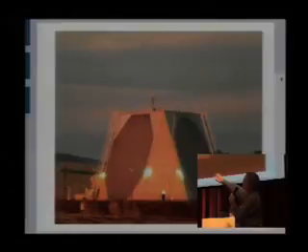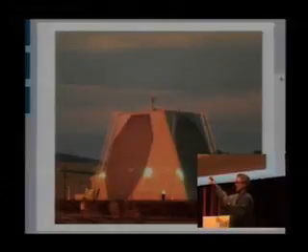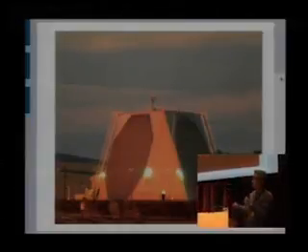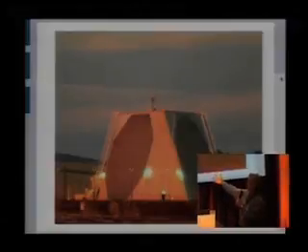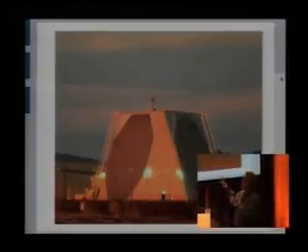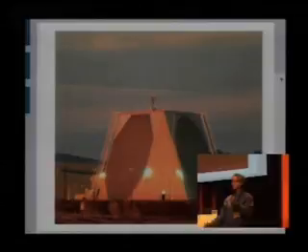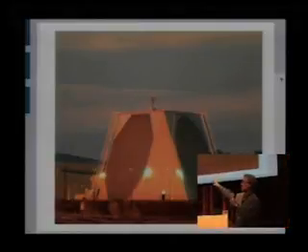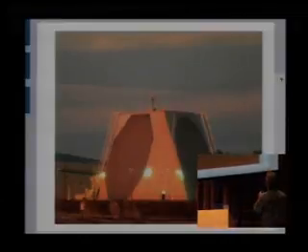Each of these big panels has about 3,000 separate antennas with transmitters and receivers behind them, and each element is about 300 watts. They're called phased arrays because by changing the phase, basically the timing, of what you send to each element, you can steer the beam around. So even though there's no mechanical movement, they can sweep the beam around. There's two of these that I know of in the US, one on the East Coast and one on the West Coast.